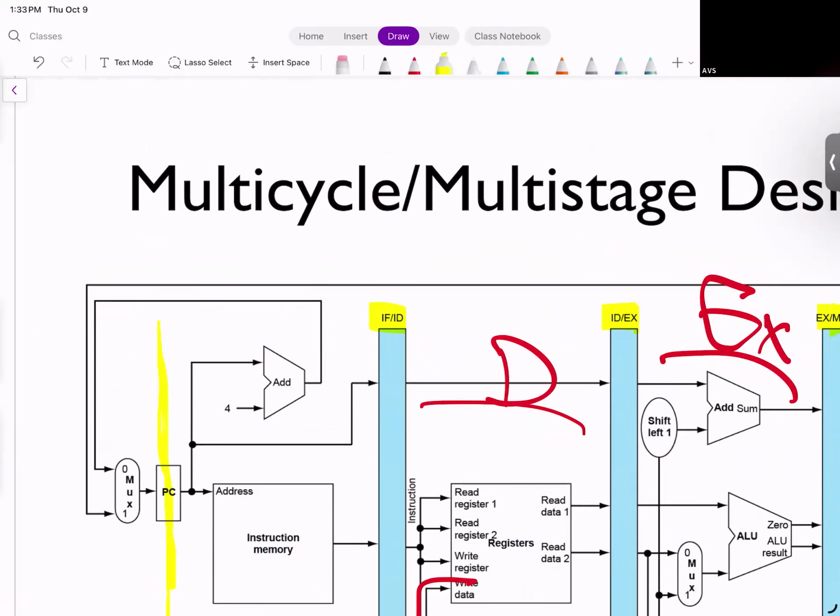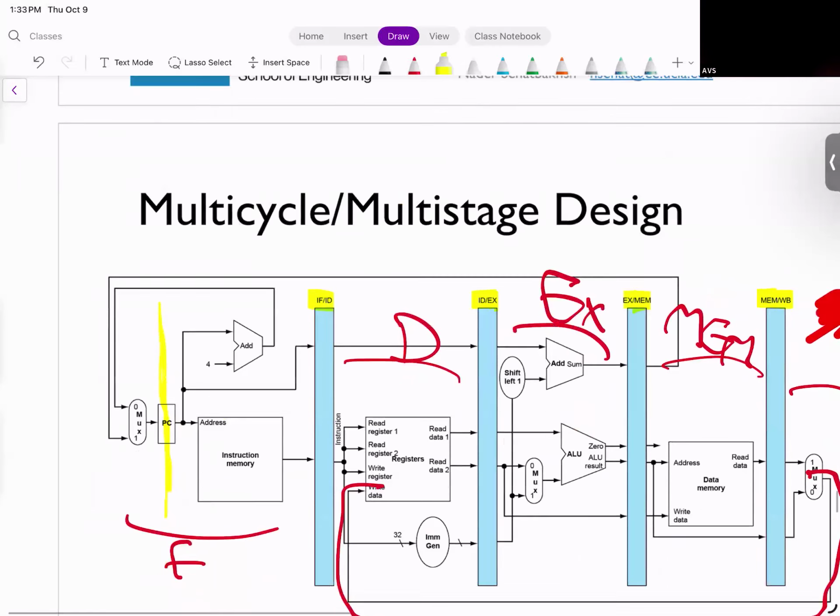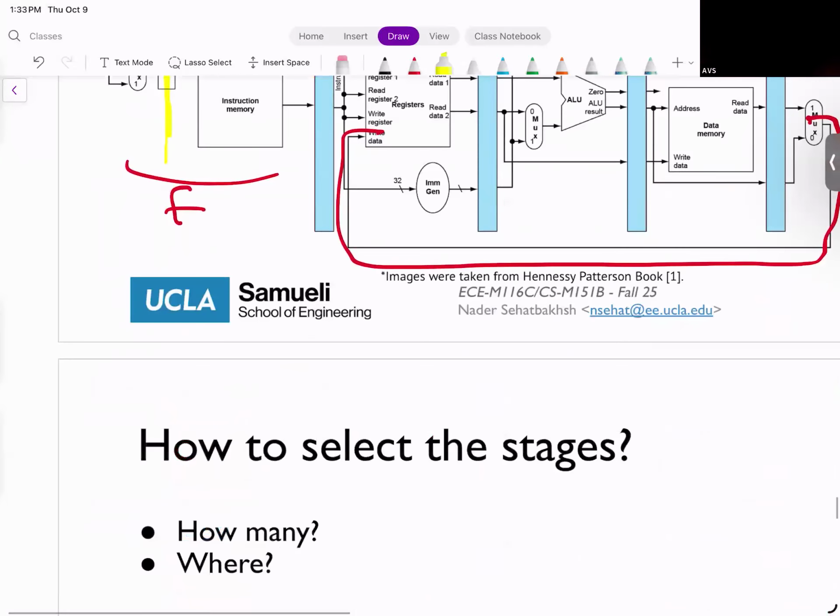So PC basically acts as the 5th pipeline register. So you have 5 registers, and these are all synchronous. The clock comes, all of them get updated at the same time. They update their corresponding outputs, and then everybody moves forward with that. Okay? Questions here? All right.